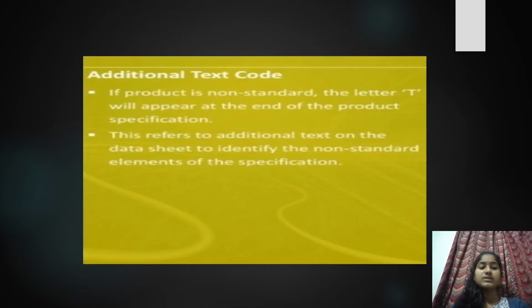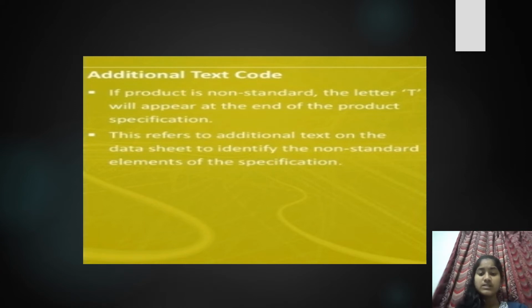VCXO circuit. The basic circuit for a VCXO comprises a standard crystal oscillator but with an electronic means of tuning or pulling the frequency slightly. This is almost invariably achieved using varactor or varicap diodes.